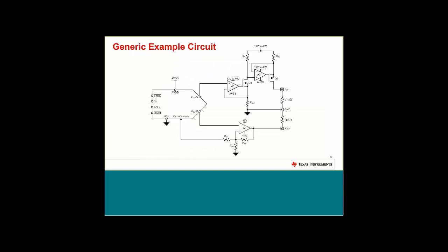Pardon me. So this slide shows pretty conventional circuitry utilized in order to realize both current and voltage output for these systems. So for the current output side, which you see on the top of the circuit, we have this so-called two-stage high-side voltage to current converter. And items of particular merit for the current output is that typically the max impedance we see someone needing to drive is about 1 kiloohm. However, for current output, it's a perfectly valid load condition to drive 0 ohms or 1 ohm, something very, very small.